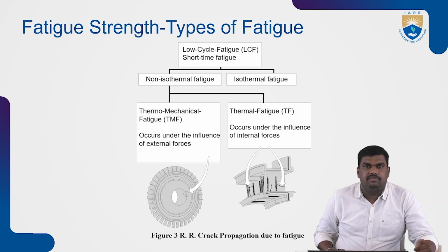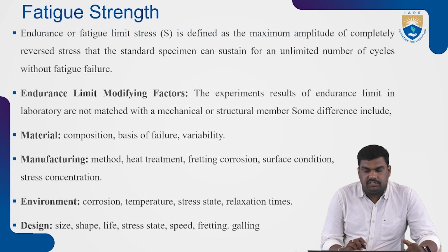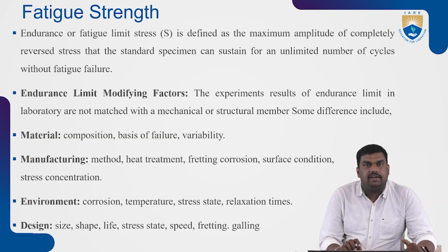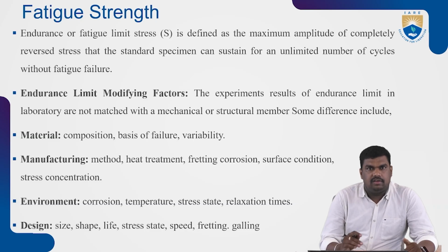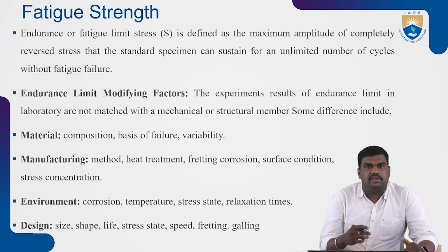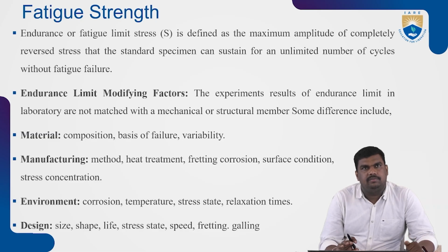And endurance or fatigue limit stress is defined as the maximum amplitude of completely reversed stress that a standard specimen can sustain for an unlimited number of cycles without fatigue failure. So that is the endurance limit or fatigue limit. Whatever load cycles are happening in the component, how many cycles it can withstand without failure, that is your endurance limit or fatigue limit.